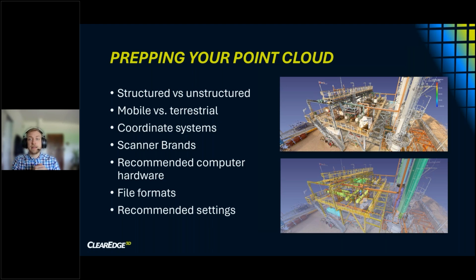And there are a lot of advantages with unifying a point cloud. It's much smaller. And so we balance back and forth. It's just the results that you want to find if you're working with structured data or unstructured data, and it's worth experimenting a little bit on what you're happy to see. One advantage of the unstructured algorithm is it is multi-threaded. So if you have a beefy workstation computer, that will run faster, and that can really impact processing time.